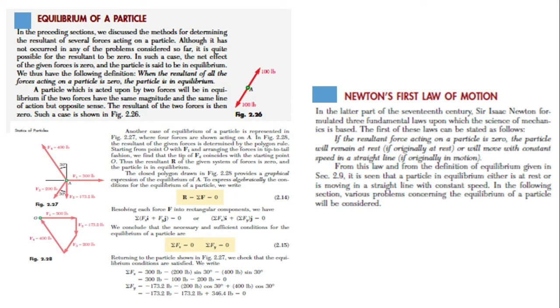Now you add up those forces and you will see that it comes out equal to 0. So is the equilibrium being maintained? No, only half the equilibrium is maintained, as sigma Fx equals 0. The picture is not complete, it is half solved. The numerical is not complete. You have to apply another equilibrium condition, which is sigma Fy equal to 0.